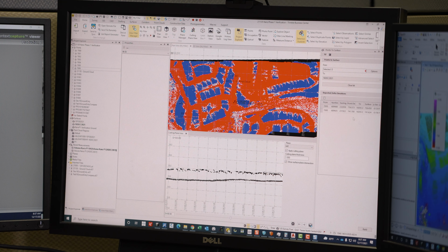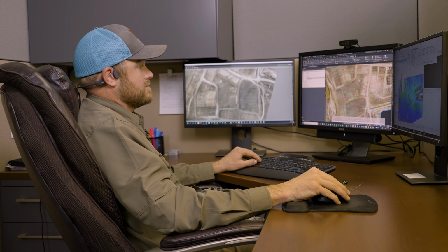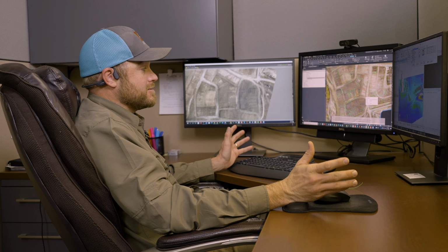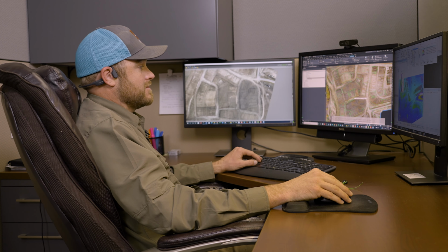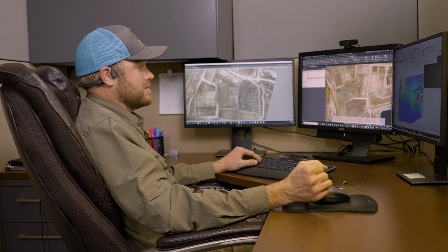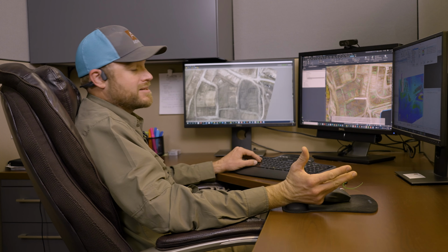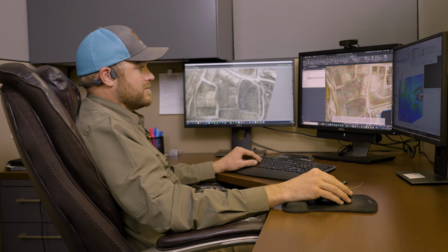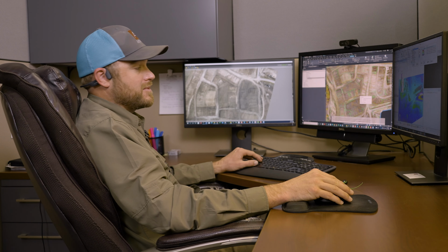So the final step is after you've done your extraction, I'll generate those points in CSV form from TopoDot, then I'll bring them into Civil 3D via their survey module. Once the deliverable has been made, the deliverable needs to be delivered. So for us personally, I'll package up the DWG, the CSV file, and the ortho in a surface export in XML, zip all that up, put it into Microsoft OneDrive, and send the client or the project manager the link.